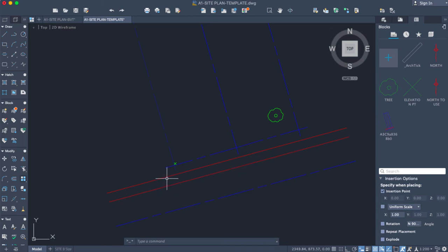So you know the spacing between the grade points or the elevation grading. So it is spaced 3.05. If you see that the grade elevation points are close to each other, you're using the offset of 3.05. If they are far, then it is 6.10.